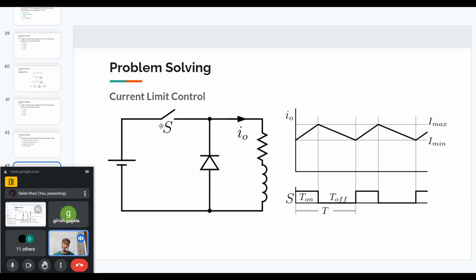Based on the differential equations, you can find the actual value of the current, and based on that, you can also find the voltage across the resistor, which will just be resistor times the current, and the voltage across the inductor will be the derivative of that current times the L, right?